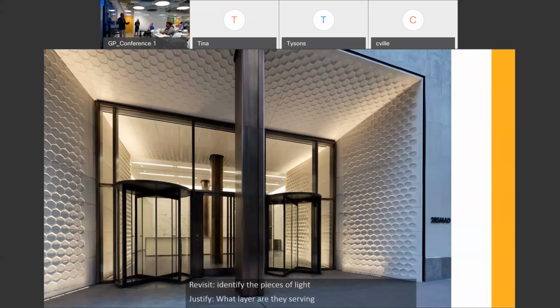So what would happen if, God forbid, value engineering comes into action and the contractor says, well, we can meet all our codes with just putting an 8-inch can there. Okay, you're still meeting that code. You're going to get a nice little scallop on the wall, still see some of that emphasis of the texture, but you spent so much time and money and detailing on this beautiful architectural element, you don't want to light it incorrectly. You want it to shine and glow and be that inviting, so it's the same as the inside.